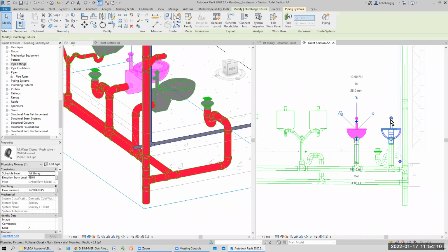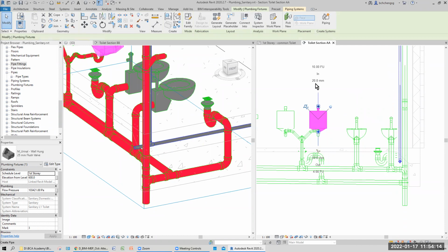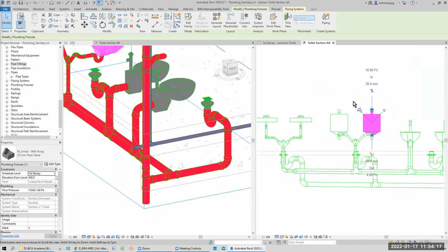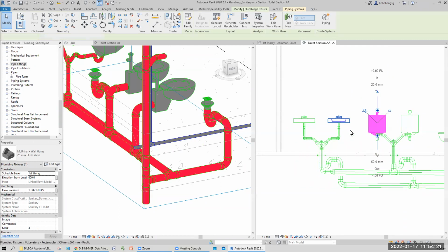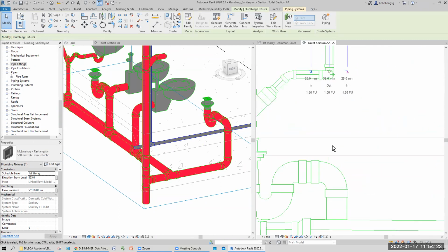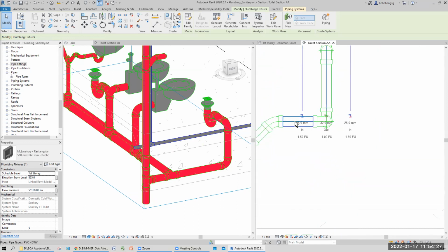See, 25, 25, and 20. This guy is using 20. Yeah, good. This is 20. This is both. You see, this guy got, oops, 25, 25. It's impossible, 25 lah. The outlet is 25, but the pipe from the heater is only 15. So there's an adapter needed.